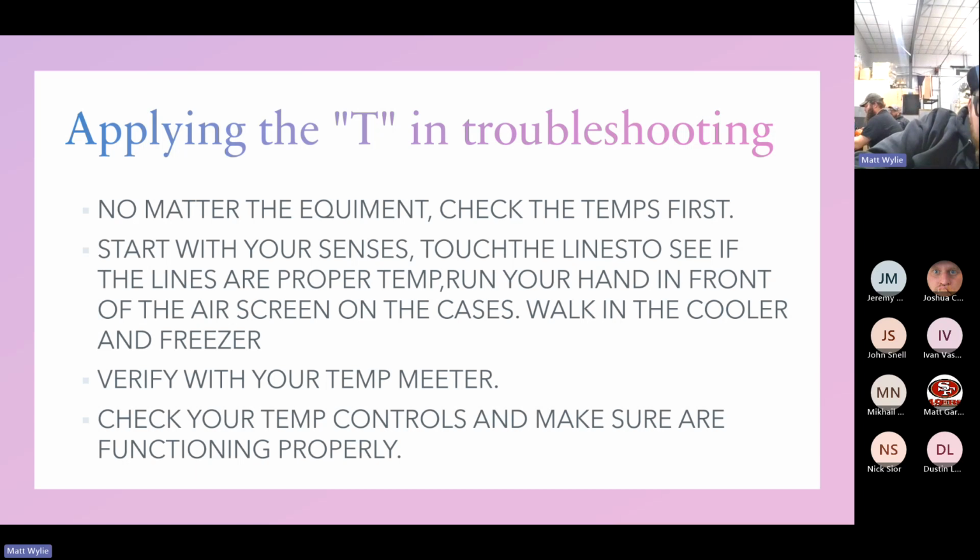Check your temp controls and make sure they're functioning properly. Temp controllers or sensors might be off a couple of degrees. The temp of the case might be reading properly, but the temperature control is 5 degrees off or whatnot.